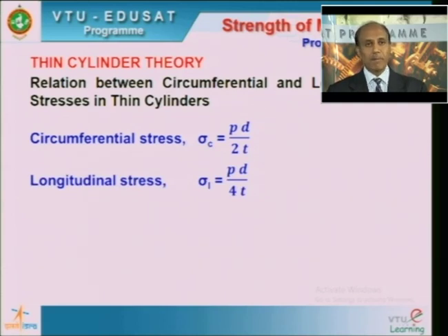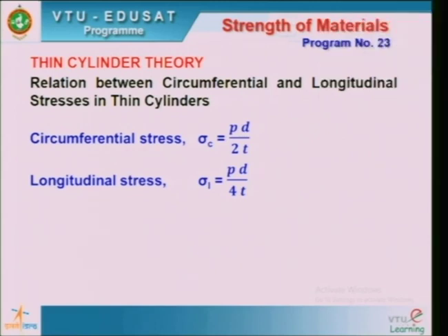Now, we compare the two. You can easily understand that the circumferential stress is more than the longitudinal stress in a thin cylinder problem, because for any thin cylinder that we take, there would be a fixed value of P, diameter and thickness.